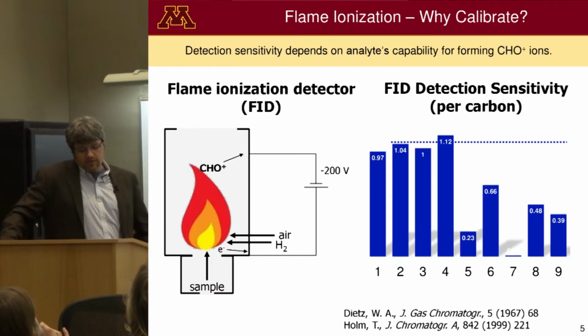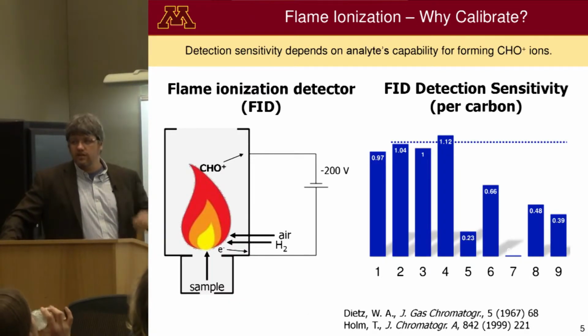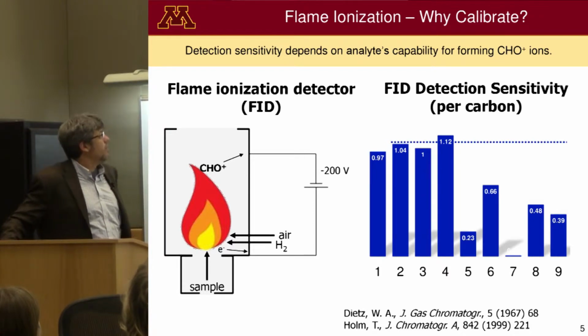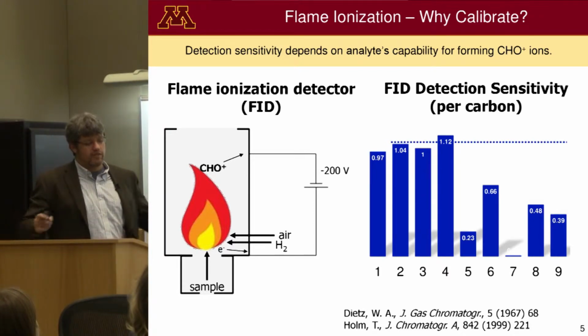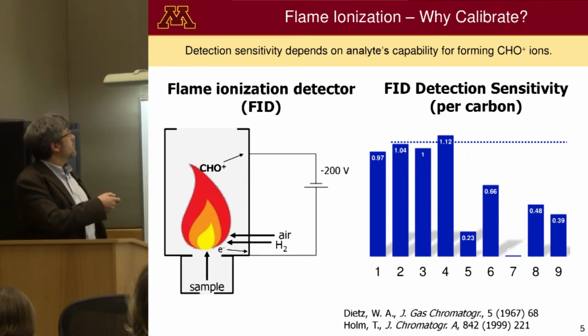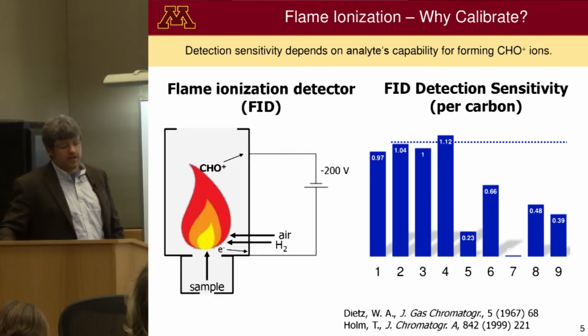So what's the problem, right? If you use a conventional detector with a gas chromatography column, once you do all the separation, right, you design your column, you'll start to see the analytes elute one by one. They'll be injected into this hydrogen flame, and then you'll start to form ions, which are then detectable, hence the name flame ionization detector.